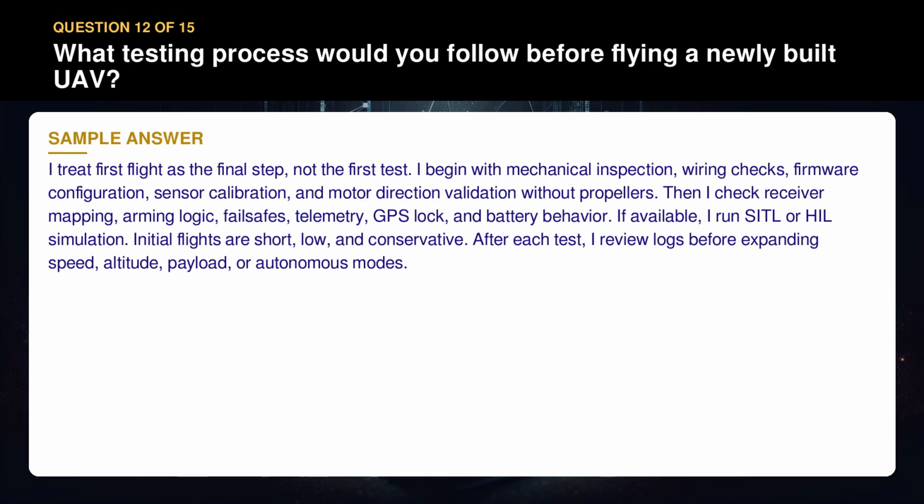If available, I run SITL or HIL simulation. Initial flights are short, low, and conservative. After each test, I review logs before expanding speed, altitude, payload, or autonomous modes.